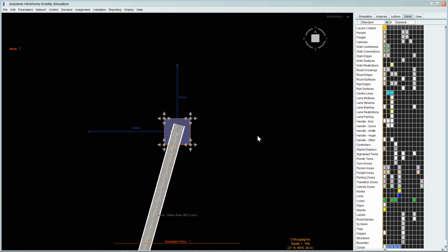If the walkway isn't fully embedded, then they won't be connected. The easiest way to tell whether they're connected or not is if the area is selected, it highlights the walkway. If I press escape, you wouldn't necessarily know that they're connected there, but if I select that area, automatically it highlights the walkway, so we can tell that it's actually connected together.